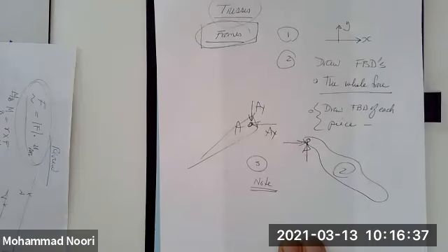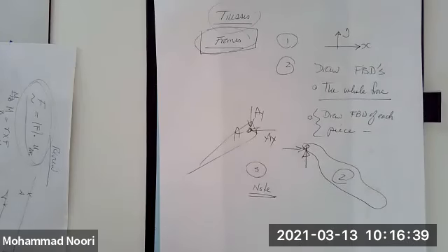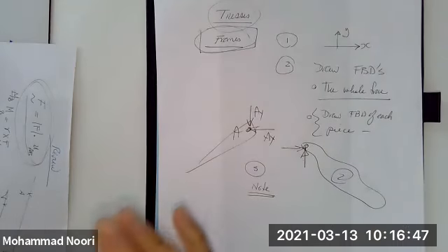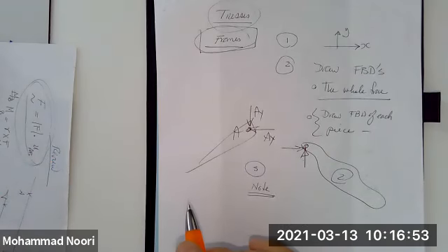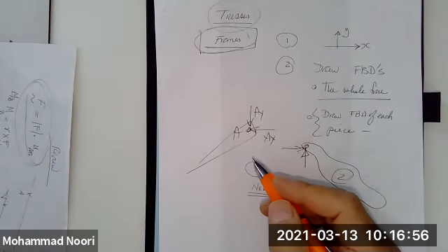If you do not detect there is a two force member involved, you cannot solve the problem. You end up with more unknowns than the number of equations. So as you take these members apart, drawing the free body diagram of each member, make sure to detect two force members because they only represent one unknown force at the point of connection.